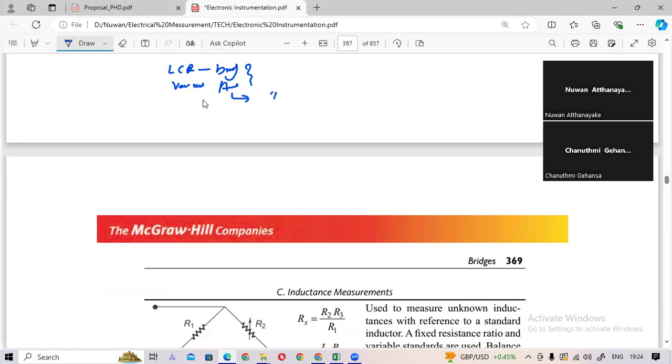Basically, we can measure DC and AC current using that setup, but using a rectifier. By adding a bridge rectifier, we can modify this D'Arsonval setup to measure AC current and voltage also. Basically we can measure DC current and voltages, but by applying a rectifier, we see how to measure AC current and voltages.